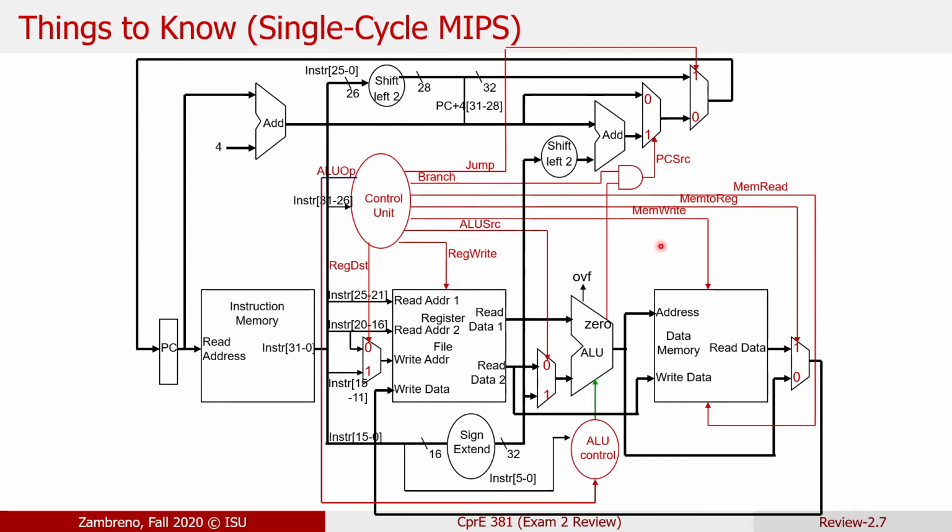So at this point, that would be my expectation for you, that we have our 5 stages of execution from instruction fetch all the way back to write back. And even in the single cycle data path, because I won't ask about the other processor design choices here, you should know what all of those control signals do, why all those muxes are there, and how it all gets tied together.